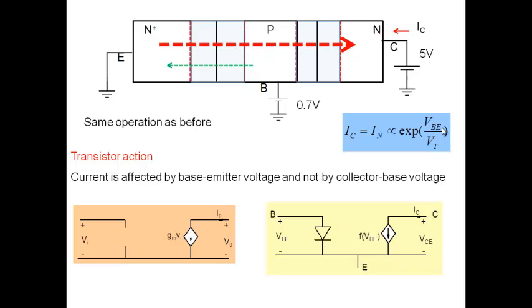So yes, we got a voltage dependent current source. So we got a current source here, which is very sensitive to voltage here, and is not sensitive to voltage applied across collector and emitter terminals. And in that sense, this is a transistor. Because the heart of a transistor is that this transconductance should be much larger than output conductance. So that's the feature that you are getting there.